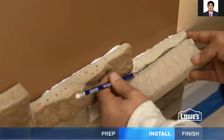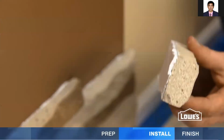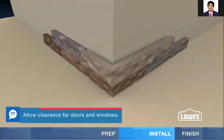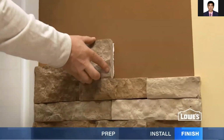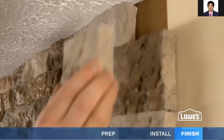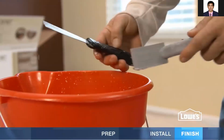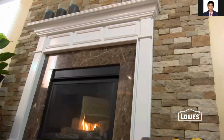To cut a stone, mark it and cut face side up with a masonry blade or hacksaw. Hide the cut edge toward the middle. For corners, reverse the special corner pieces with each row. Continue installing, periodically checking for level, and wiping off any adhesive that gets on the face of the stone before it dries. And that's all there is to it. Cleanup is as easy as using warm water for interior adhesive. An ordinary wall gets an extraordinary makeover with the natural beauty of stone veneer.